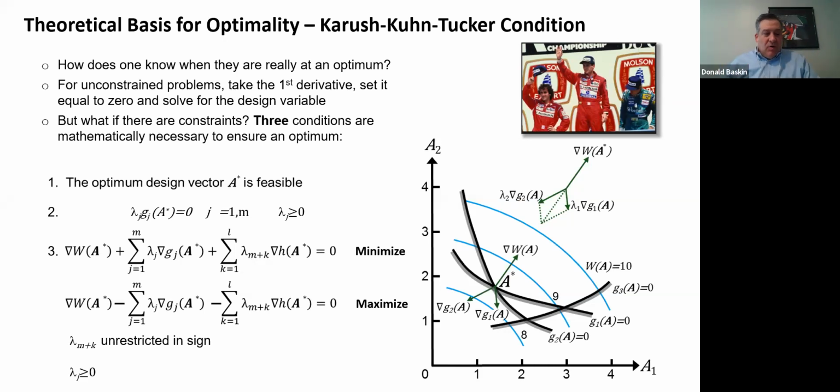So you will probably never really encounter these when you use a program like OptiStruct or Genesis or other optimization software. Even there's numerical optimization software that's nothing to do with structural optimization or light weighting. Those software packages all have the Kuhn-Tucker equations or conditions programmed into them. So that's the condition that they will use to determine when they've hit a maximum or minimum.